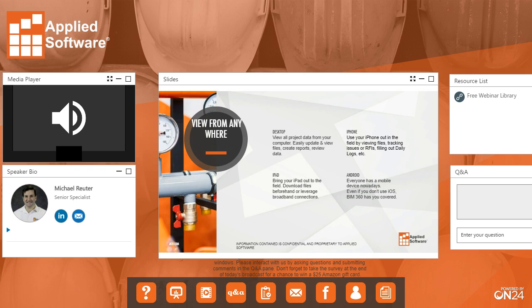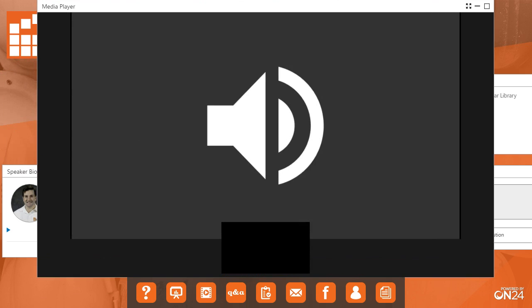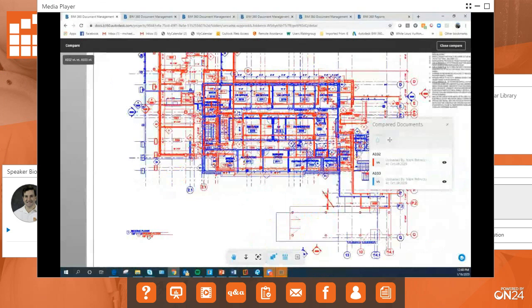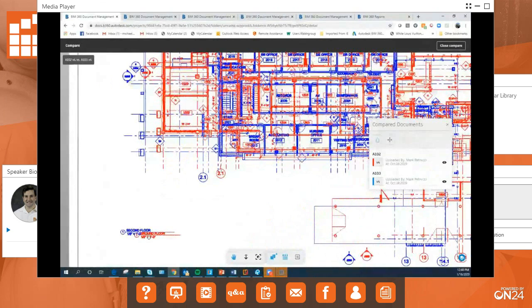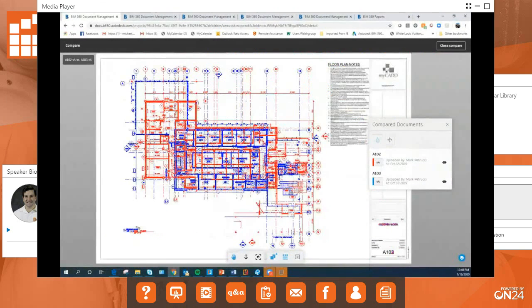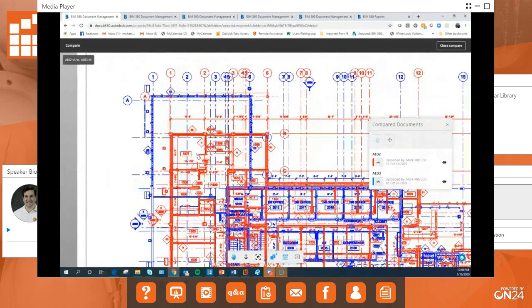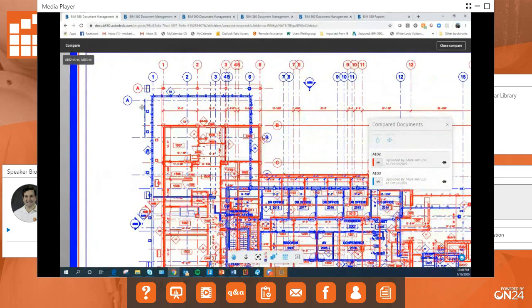on your computer's desktop. Okay, so if you look at my screen right now, what I've already gone and done is I'm comparing the ground floor versus the second floor of this building. So you can see right off the bat that these pages don't line up. So it's pretty easy to line up. I'm just going to hit align, and then I'm going to move one.